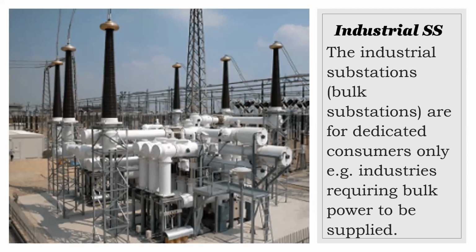So in Jamaica, whilst our industries are, within the scheme of things, relatively small, they would be supplying the full 24, but maybe in other parts of the world they may be supplying 132 kV to the facility. That facility would then put in their own substation, which is what we are looking at here, to distribute power within the facility. All right. Is that clear enough?